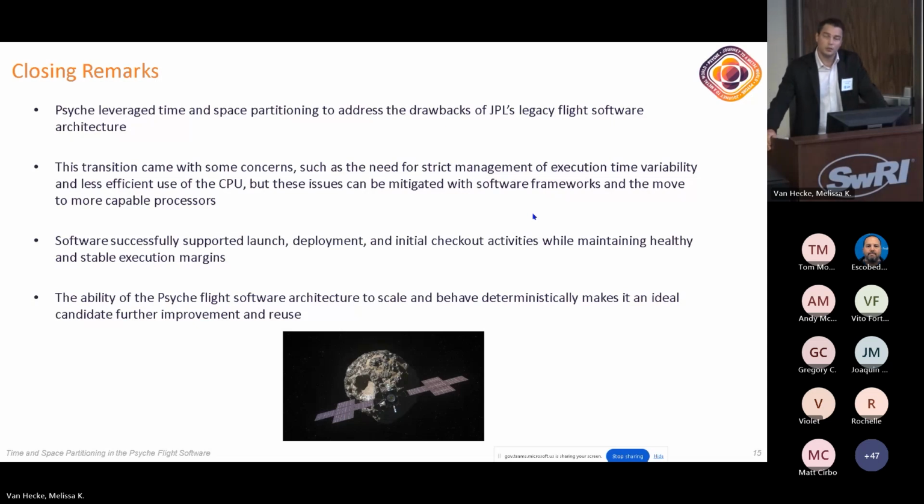So we had a framework that we wrote in the software that would give us high resolution measurements. We tracked average case for every module, and worst case for every module and partition. And then we looked at the margin by what is the total amount of time that we have in the partition window, and what percentage of it did we use in our absolute worst case.